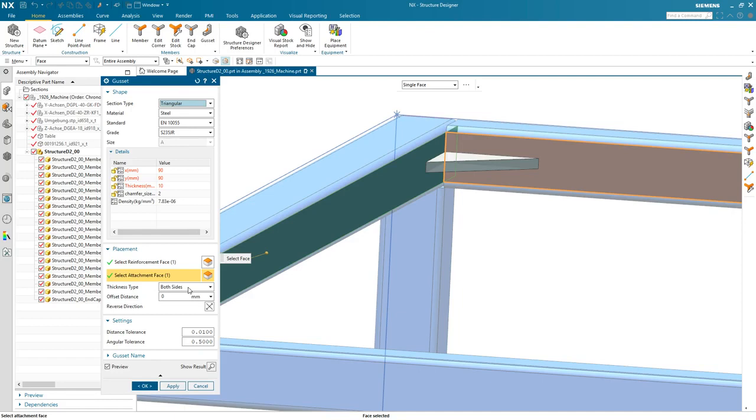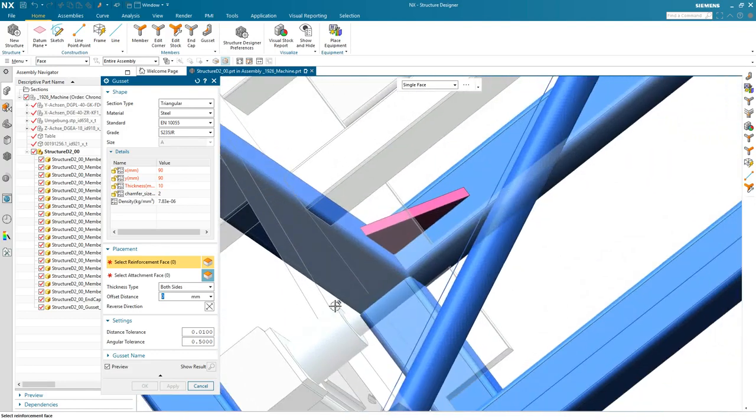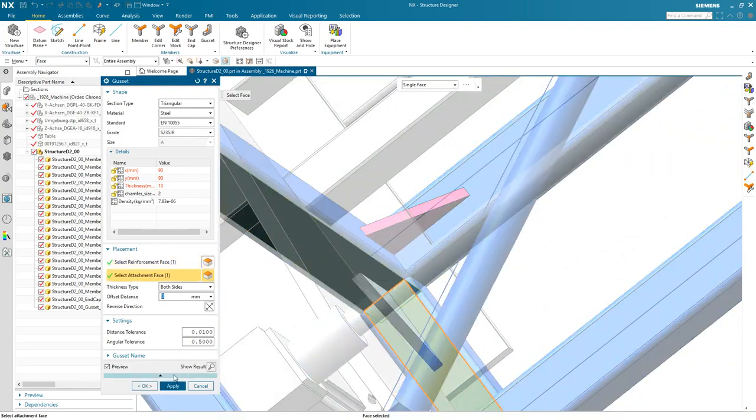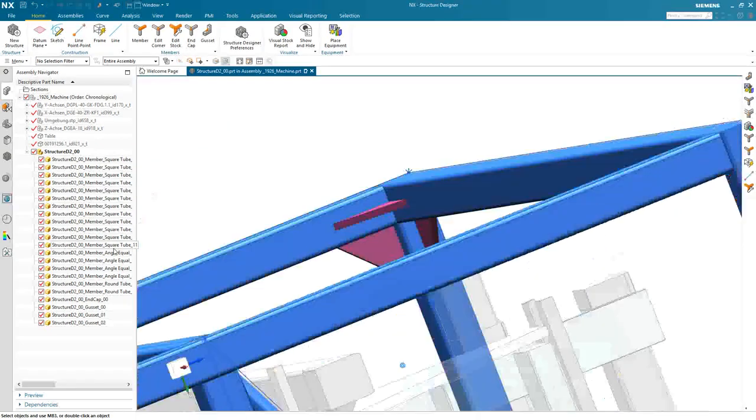You can even control the thickness, whether it goes to both sides, the inside, the outside, and you can even kick it over to one side or the other, depending on what your actual design conditions are. We'll rotate this over, and we'll add a couple more gussets to the inside of our model. That's probably going to be good enough for right now, a good stiff corner.